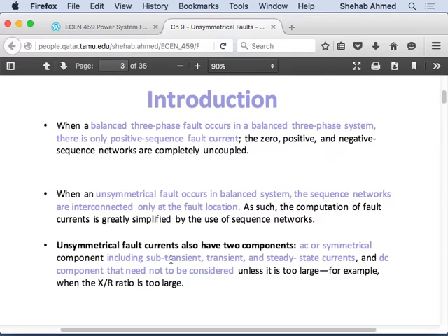It's important to know that the impedance of a generator during the fault goes through different values, and you will typically have to select one. When you have a very high current flowing in the system, remember from your 322 electromagnetics class, if you have two bars with currents flowing through them, there will be a force generated. This force is something you have to account for in the mechanical design of your equipment.